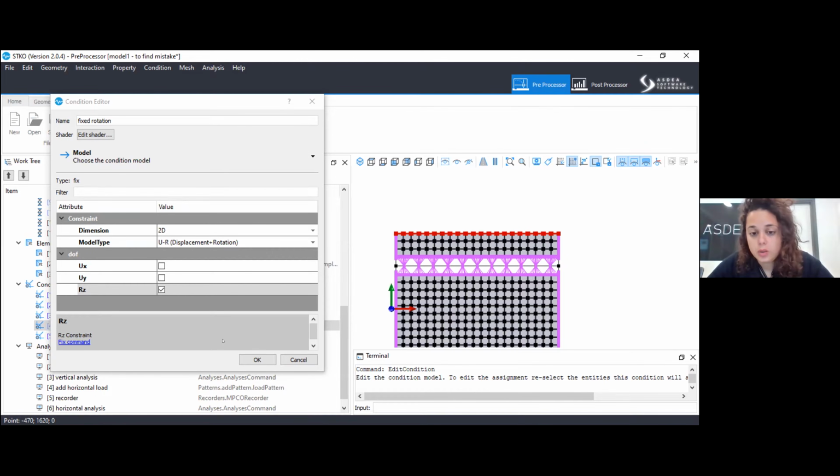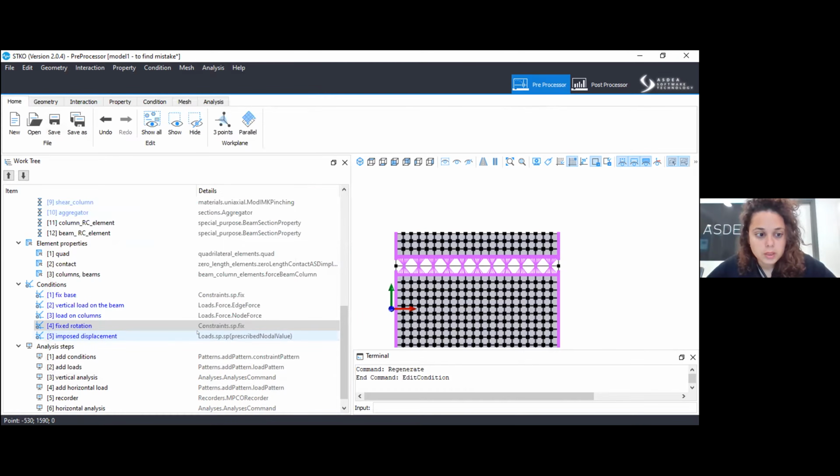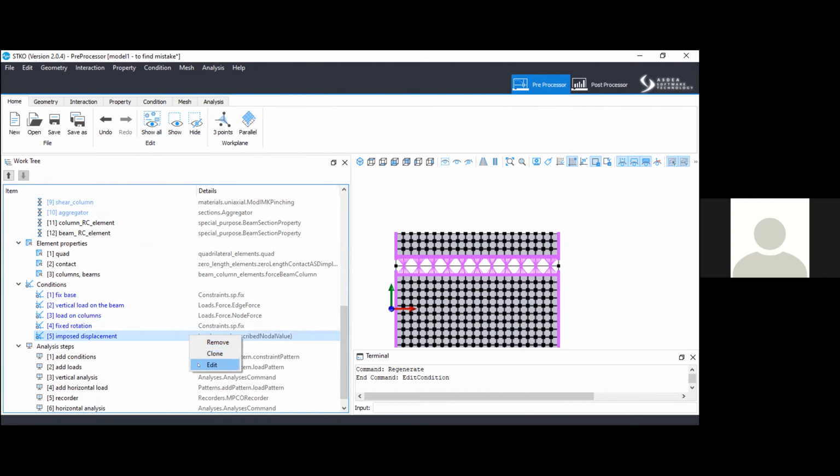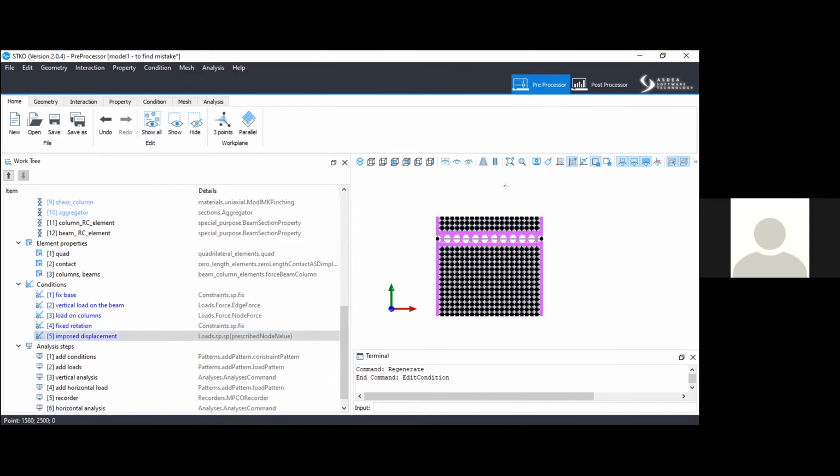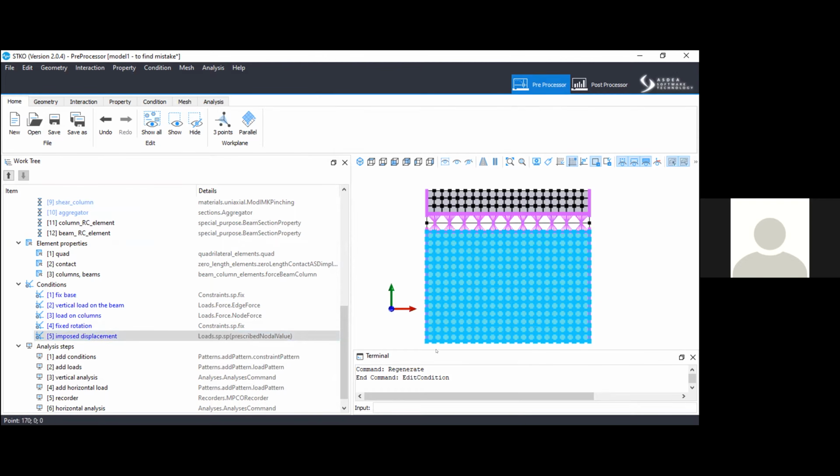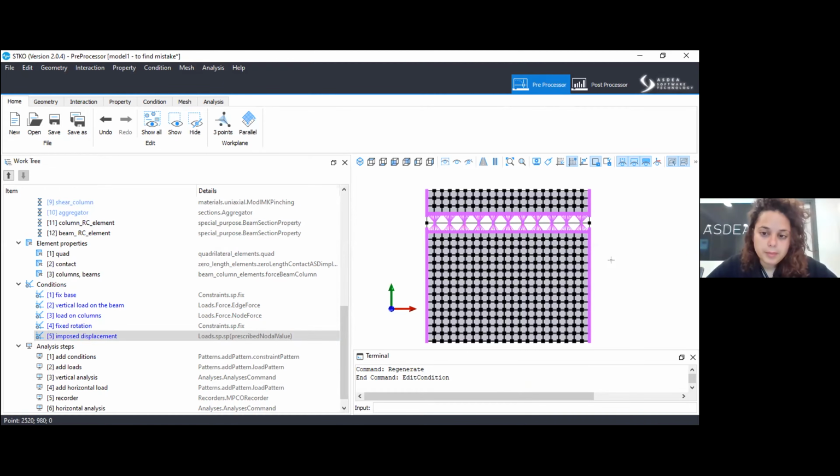But in your case, you don't have an additional rigid element to connect. You can just apply a fixity there. Okay, I will think about it, because experimentally they applied vertical load to the masonry through the metallic beam. So it can also be considered as we prevent rotation, but I will think about it anyway. But maybe you can model the metallic beam and then attach your infill panel to that beam with an equal depth like you did before.